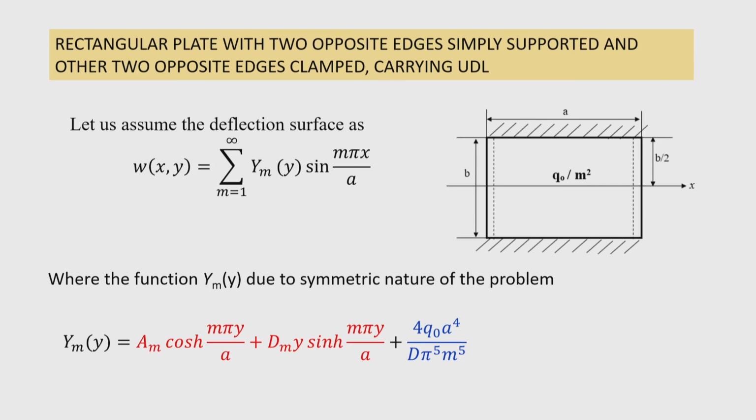Then we have the reinforced concrete slab, where the slab is supported by a beam which is integrally built, that means monolithically cast. Therefore, a fixed condition develops at the end. So, fixed conditions are common and therefore we cannot ignore them, and with the help of Levy's method we can easily encounter this condition.